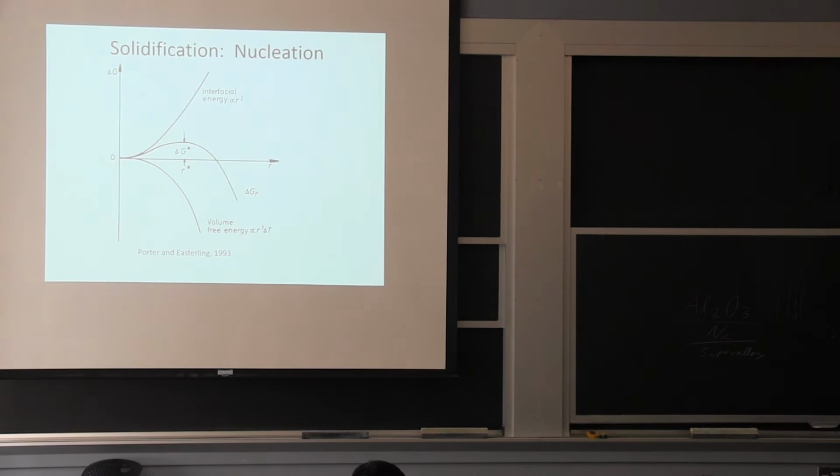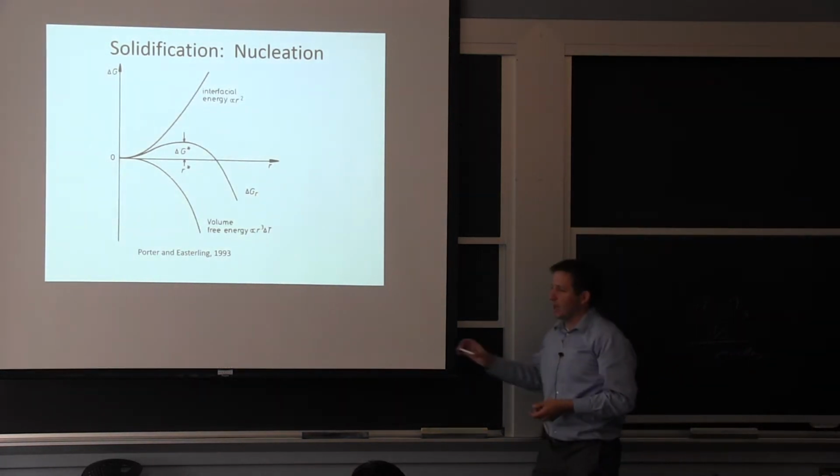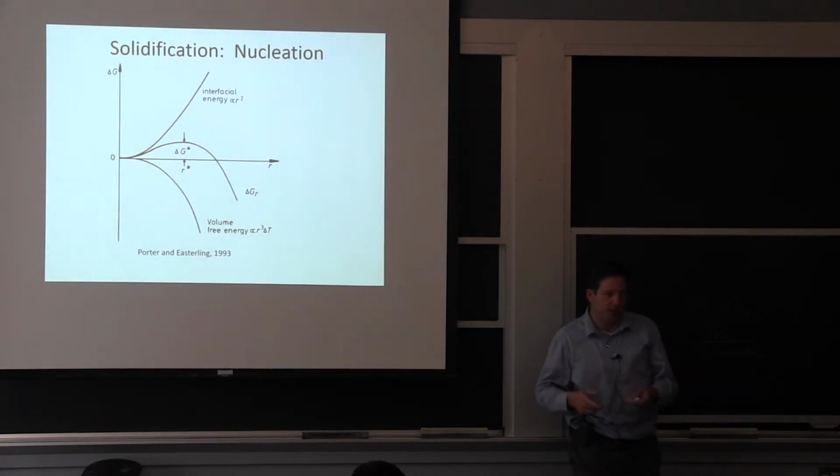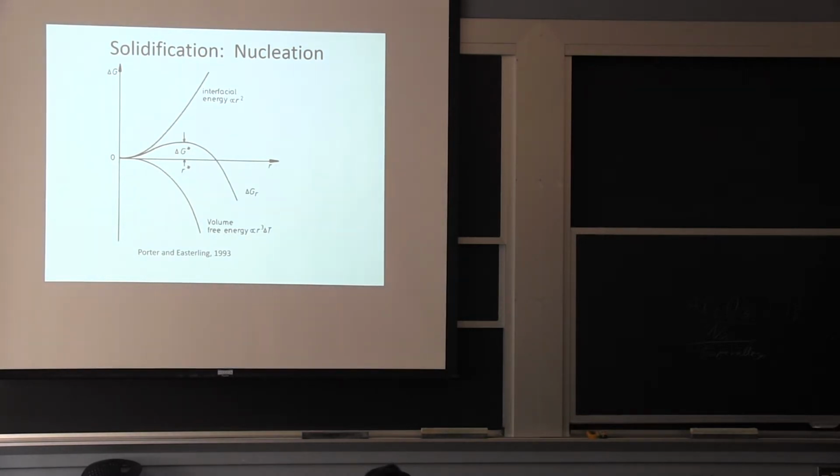We're going to go quickly through what we've talked about these 12 lectures. And I think I've been trying to bring back some of these key concepts. We talked about nucleation for the reason that if you're going to go from a liquid to a solid, which was our first topic, solidification, you have to wait long enough so you have all the temperature fluctuation creating this little nucleus that's big enough that you're willing to live with all the surface tension that you created around the particle. And that's the critical nuclear size.